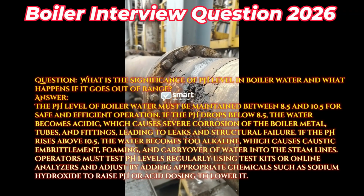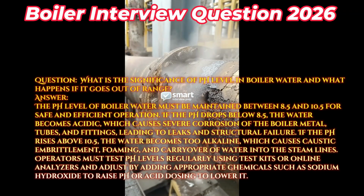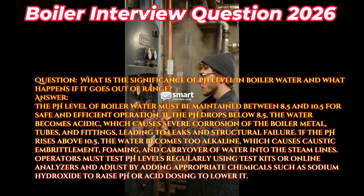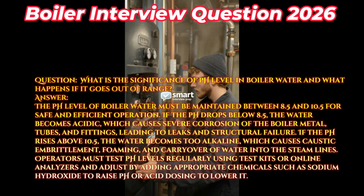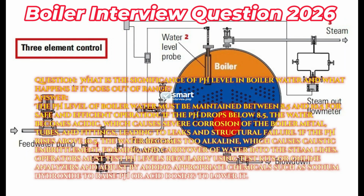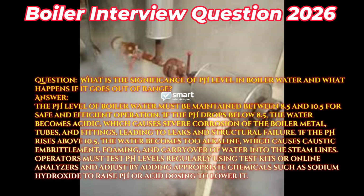If the pH rises above 10.5, the water becomes too alkaline, which causes caustic embrittlement, foaming, and carryover of water into the steam lines. Operators must test pH levels regularly using test kits or online analyzers and adjust by adding appropriate chemicals such as sodium hydroxide to raise pH or acid dosing to lower it.